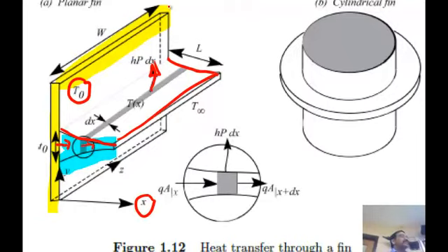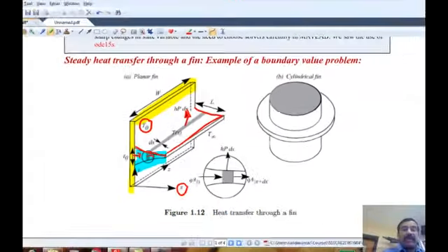So what happens is, when you pump energy into a metal, that energy goes to increase the vibrational and the rotational energies of the molecule. And that we call as representing the temperature. So the higher the temperature, the higher the energy is. So temperature is an averaged macroscopic quantity. The phenomenon itself is occurring on a micro scale, on the molecular scale. So whenever you set up a temperature gradient, the heat is going to flow, as if the electrons are flowing in the case of electricity, from the base of the fin to the tip of the fin.